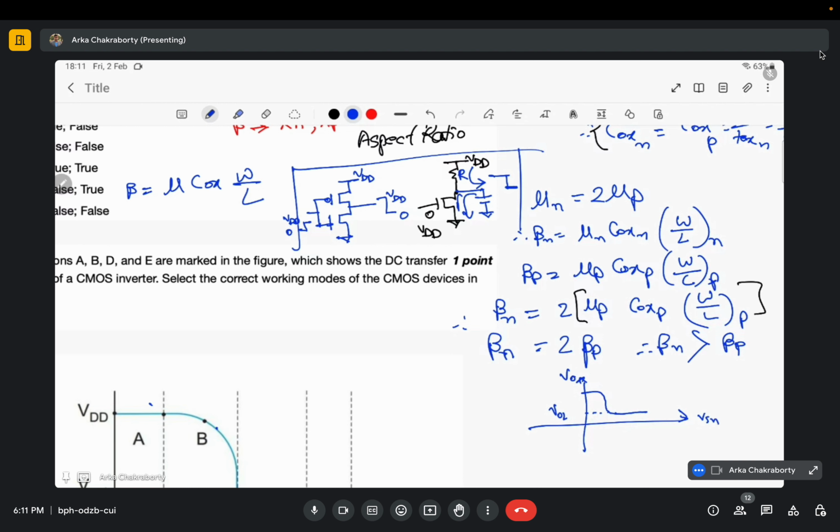So there will be a competition, a struggle, between this resistor and this transistor. The resistor will try to charge the output load CL to VDD, and this transistor will try to discharge it. Generally the strength of this MOSFET is greater, so my V out would be low, and when this transistor is made much stronger, the V output low can be made very small.